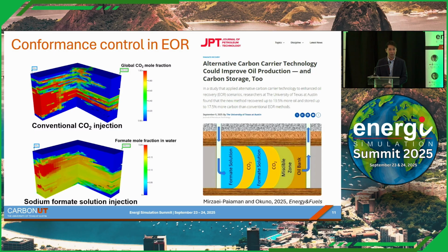The first is continuous injection of CO2. The second is a CO2 WAG. And the third one is another WAG, but the water slug was replaced by sodium formate solution. So between the first two, continuous CO2 injection is better in terms of CO2 storage, but worse in oil recovery